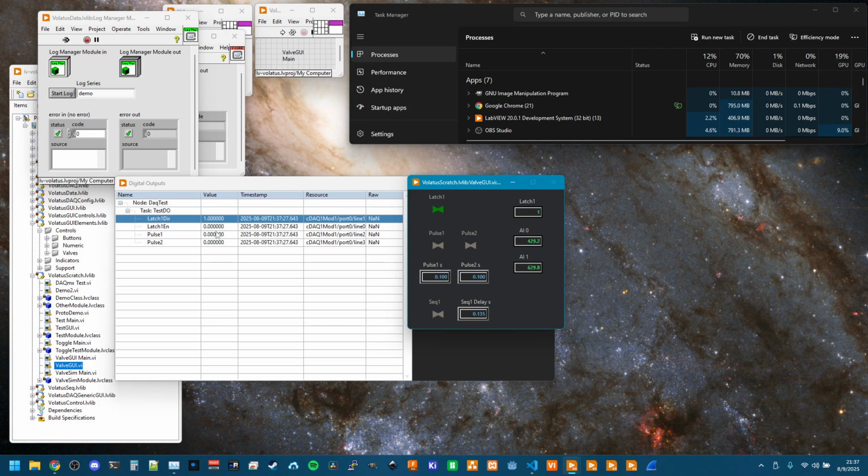So we're going to open this valve by setting the direction to 1, and then if you looked closely, you could see the latch 1 enable blink at a 1 for about 200 milliseconds. So that makes it easy with just a simple front panel valve control to get that kind of coordinated functionality.